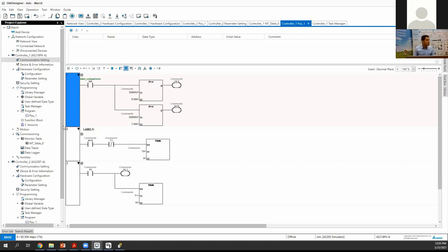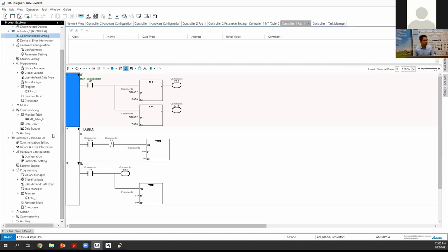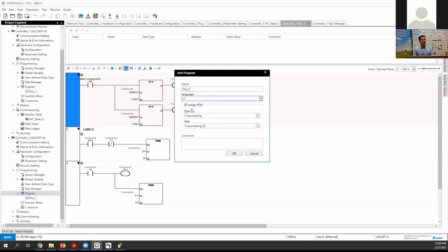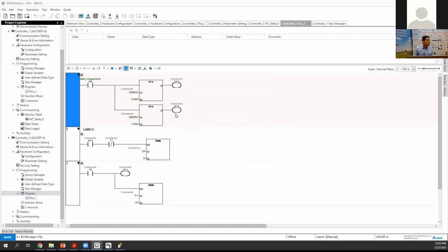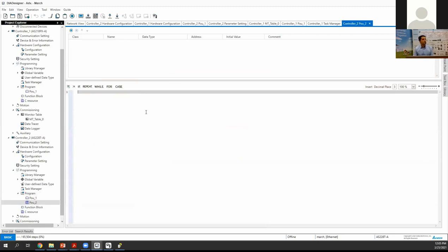So let's have a look also the structure text part quickly. Okay, so for the structure text, again we go to program and right click and add program and add ST language. So this is the part we choose our language for PLC programming. So this is the part we define the code. So here again, what we can do, we can work as address based or variable based. If you want to work as variable based, first you need to create your variables here.